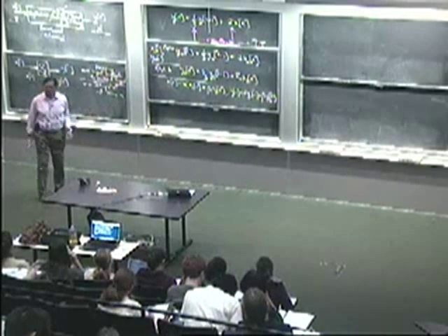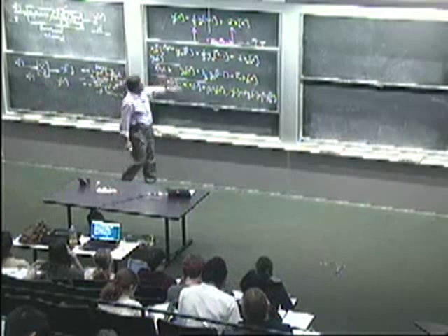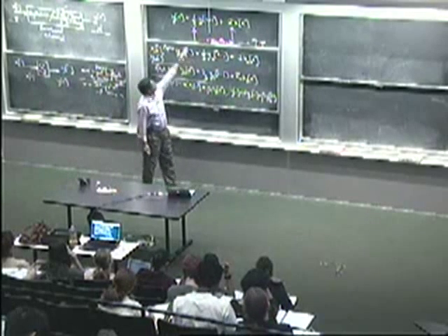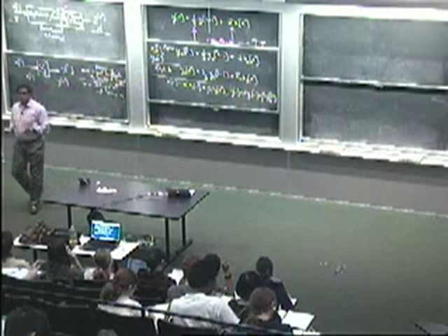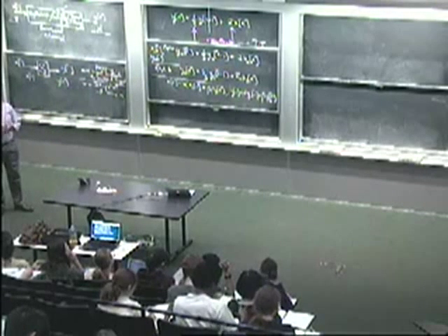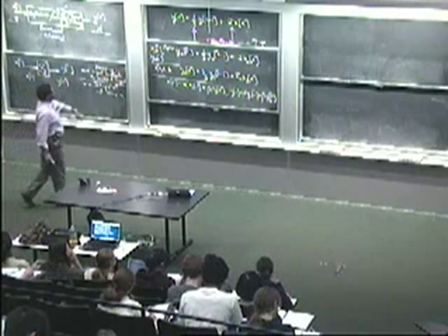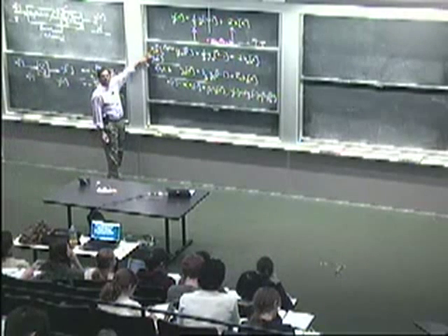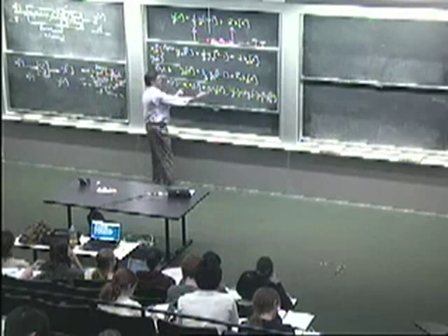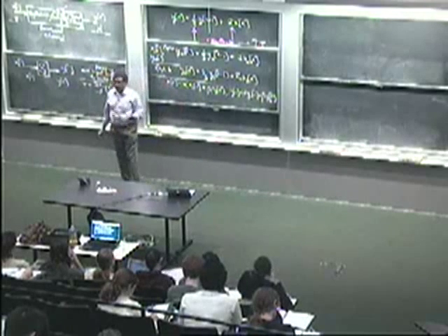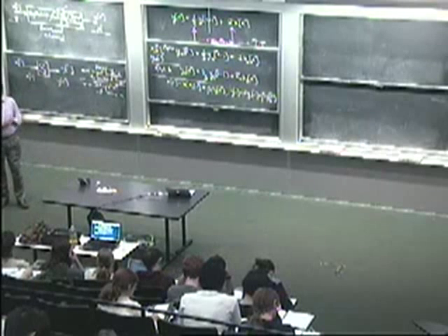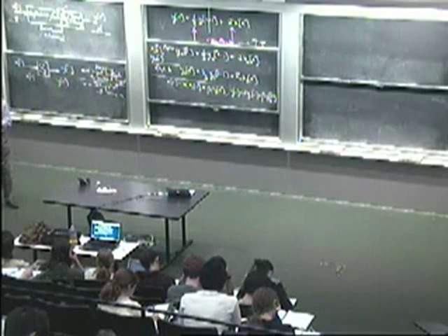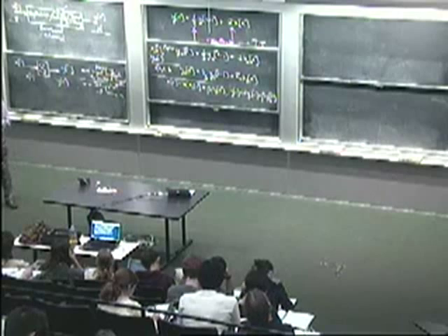So when you substitute these in, you'll find that x[n] defined this way and y[n] defined this way will actually satisfy that equation. So this is what superposition requires you to test. If it's true for every possible pair of experiments here and every pair of weights alpha and beta, that the superposition satisfies the equations governing the system, then what you have is a linear system. Okay?